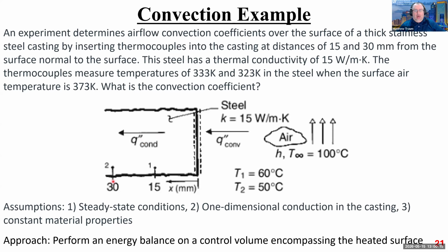Okay, the book told me that I can, I think the book told me, oh, no, no. Okay. It didn't give me any assumptions. So I'm going to make some engineering assumptions, which I think you guys are skilled at from your other classes. So I won't delve into this too deeply, but here are the assumptions. So first, we're in steady state. Second, we have one-dimensional conduction in the casting. And third, we have constant material properties, so constant k.